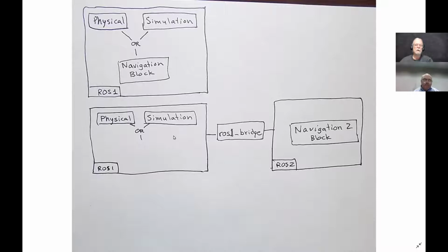Other things I know directly, if I want to run the CAN interface, I can directly run CAN and all the pieces on ROS 1. And again, then I just have any additional stuff I can put on ROS 2. So at this point, you can get just a simple thing. I guess one of the simplest things is go to ROS 2 and from a command line say, create an Ackermann message, which should come all the way back through and go to the simulation with the ROS block and make my vehicle move, and then just work up from there.